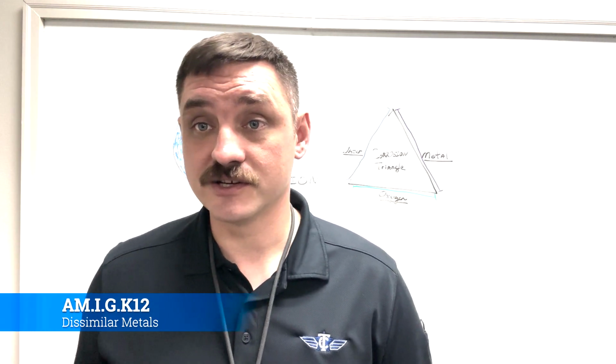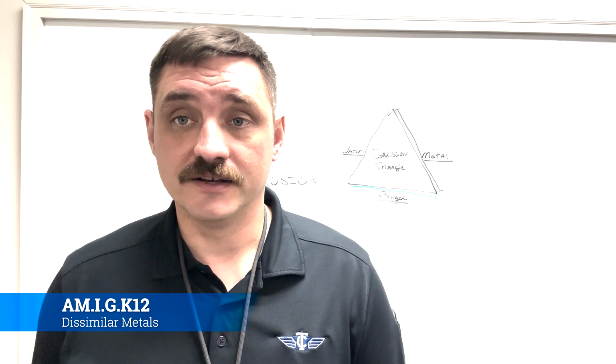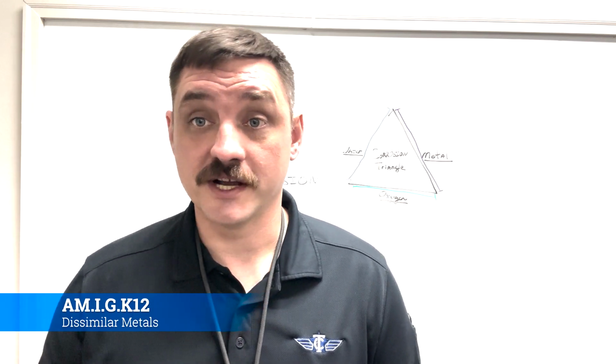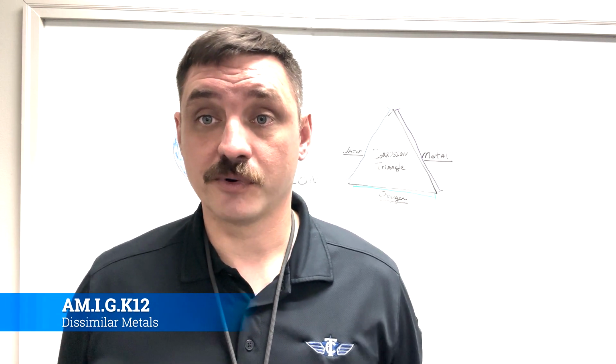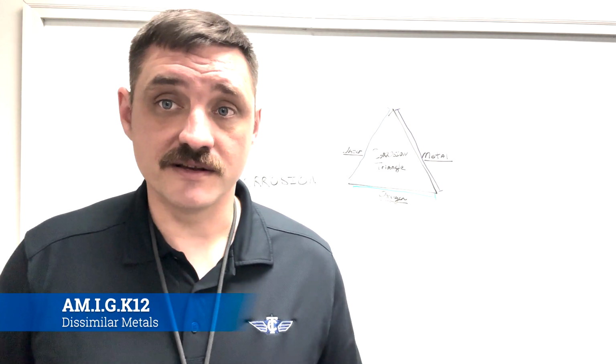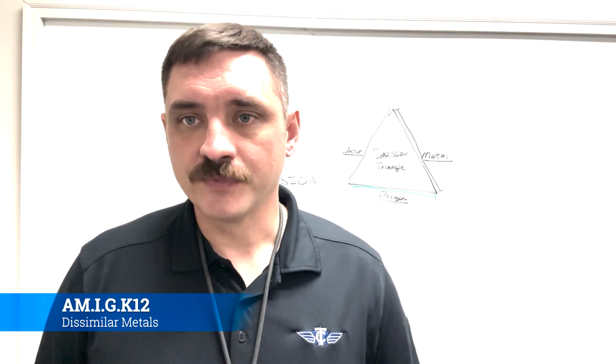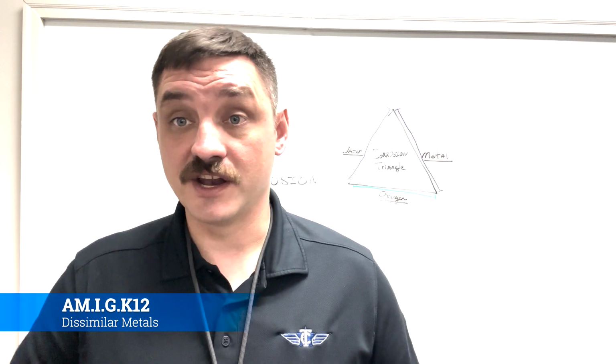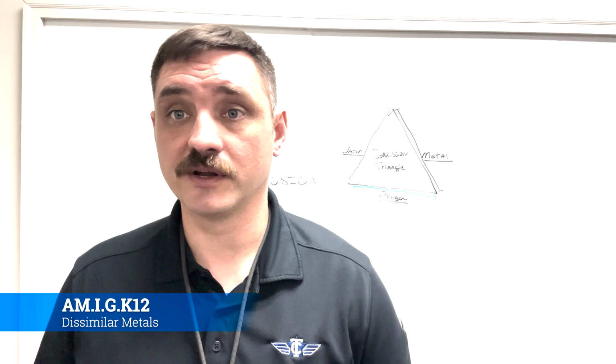The reason it's there is corrosion. It's a corrosion inhibitor. So you spray it down once, you spray it down twice. If it's on the outside of the aircraft or something you want to look pretty, you'll put primer on it, then paint, up to however many coats you need. So that's non-magnesium dissimilar metal protection.